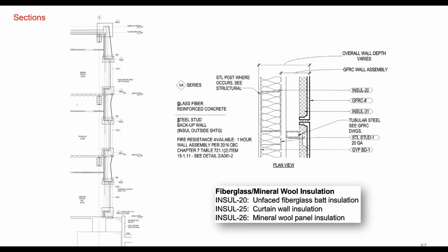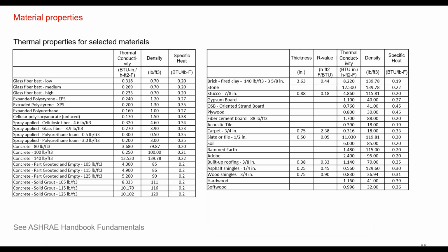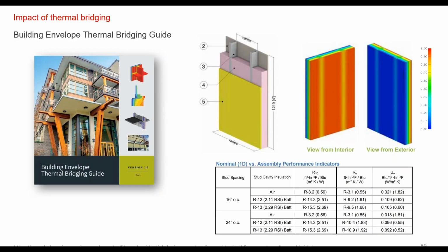So from that, you could likely look at Appendix A in 90.1 and look up the performance of that assembly. And sometimes you might also have an energy code filing, and that filing might actually have these things already pre-calculated for you. If there's an envelope consultant, they might have already determined what this could be. But likely you will be calculating what that looks like, so you're probably building up a set of layers, and from those layers you're creating assemblies.